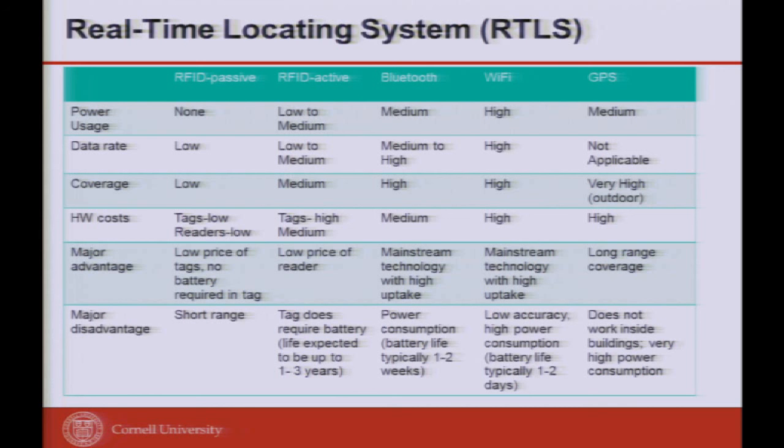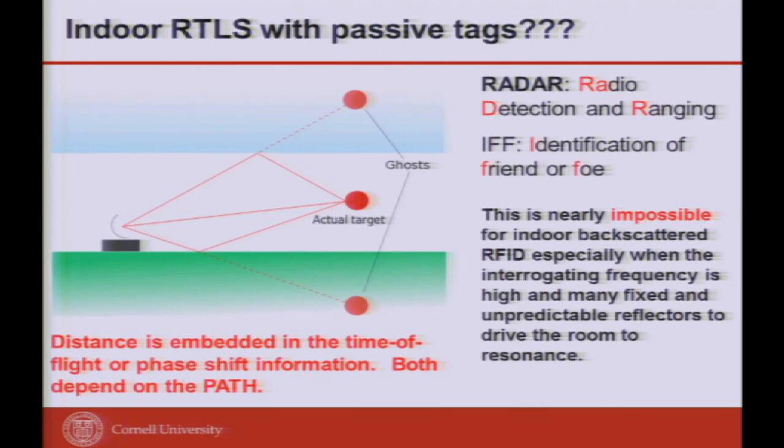There are two things to keep in mind. Because of the reflected wave, the range is coded in there by the phase shift. But you have two problems: the phase shift is represented by a bandwidth, and you don't know the phase shift beyond every quarter wavelength. That's the ambiguity point. Although phase gives you much more reliable and accurate locating information, you have to resolve two things: the bandwidth issue and the wavelength ambiguity. Focus on that.